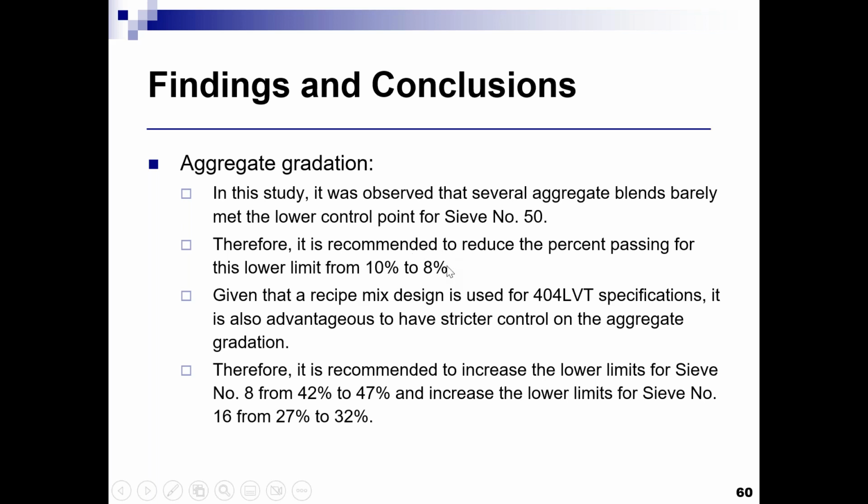So you can actually relax that if you can show from laboratory testing that you are getting good performance. And that's basically what we did, that we were getting the 9s and they were still performing okay, so we lowered that limit. Still, it's important for the mix to include finer portion of aggregates. You don't want it to be too small to the point where you have basically no finer aggregates in the mix. This is why the 8, basically.